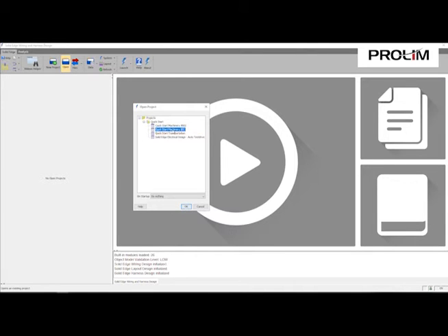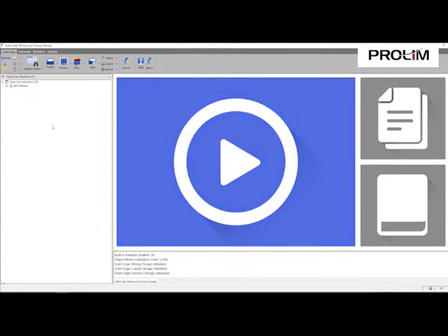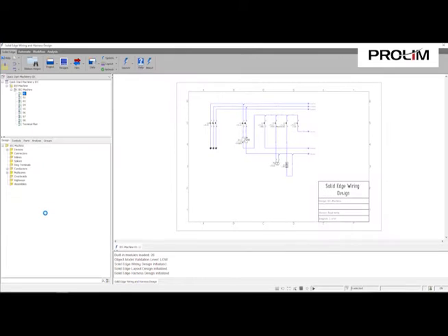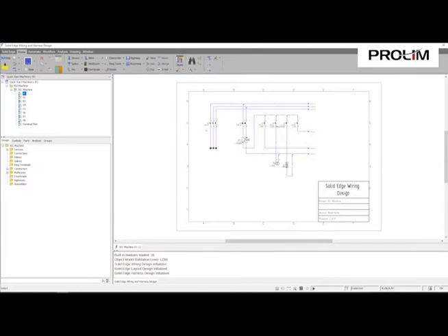So I'm going to go ahead and select, and as you can see here, even though I only did the IEC loaded database, I still have access to the ANSI and the Quick Start. But there's some back-end accessible options and features I have specific to the IEC database because I selected that in the beginning of the install. Let's look at the machinery IEC database. I'm just going to open up this quick machine sample, and open up page 1 diagram. And here we just have a simple 2D wire design.